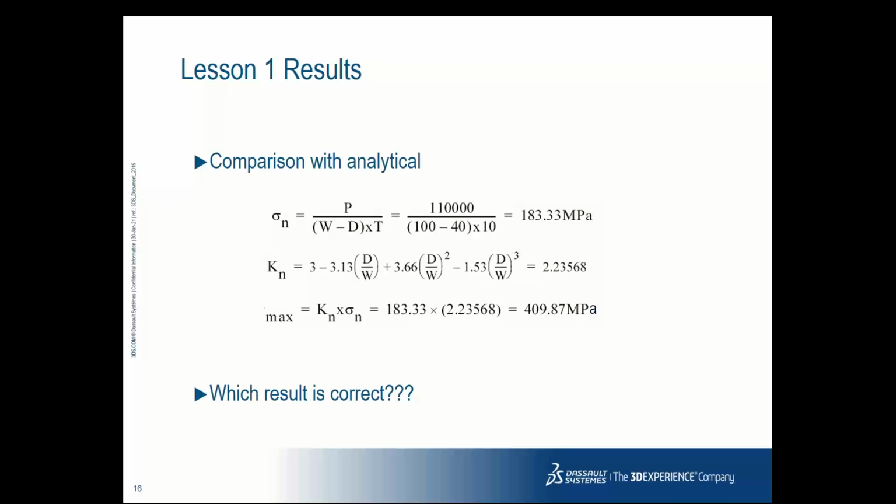Suppose on site I am getting the stress value as 350. FEA will tell you that while you perform the FEA analysis, the stress values may come around 320, or they may come around 310, or they may come around 340. So you will get close to the actual results with the help of FEA. I'm again repeating that FEA won't give you accurate results. They may give you an approximation of the actual value. No software in the world can give you this, because all the software is formulated based on numerical methods, which are based on approximations, and they don't give you the actual values.